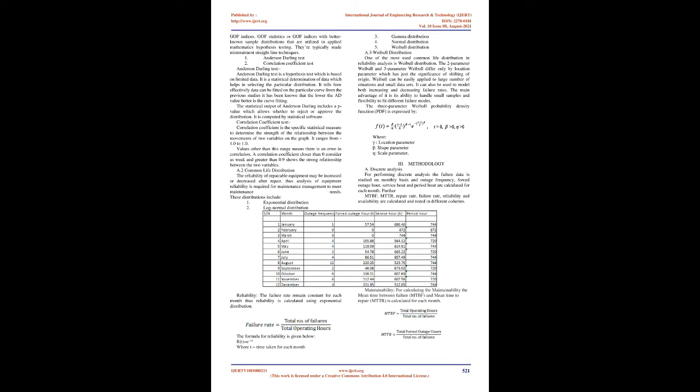Literature review. There are various methods to analyze the performance of a system using RAMs. RAMs is a logistic tool that estimates the performance of equipment at different levels. It directs safety and operation problems and finds the area in the system where refinement work should be done. Certain key performance parameters such as mean time to failure, MTTF, mean time between failure, MTBF, mean downtime, MDT, mean time to repair, MTTR, and availability, A, values can be determined to perform the analysis.